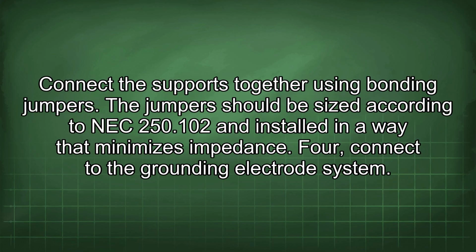3. Install bonding jumpers. Connect the supports together using bonding jumpers. The jumpers should be sized according to NEC 250.102 and installed in a way that minimizes impedance.